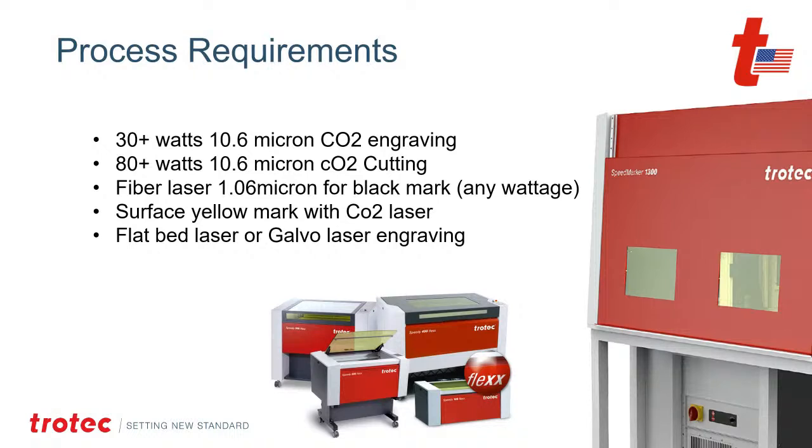30 plus watts at 10.6 micron CO2 is for just engraving with your CO2 laser. You can have about 30 watts and above. Any lower wattage, it probably can still work with, say, 20, 25, but it's just going to be pretty slow. 80 watts and above for CO2 cutting. It is a denser material than, say, acrylic, and it does require a lot of laser power for cutting.